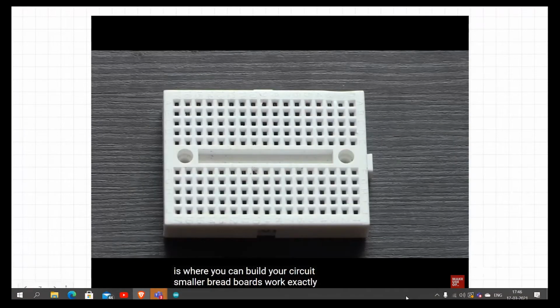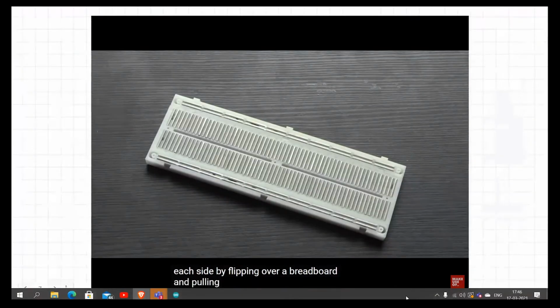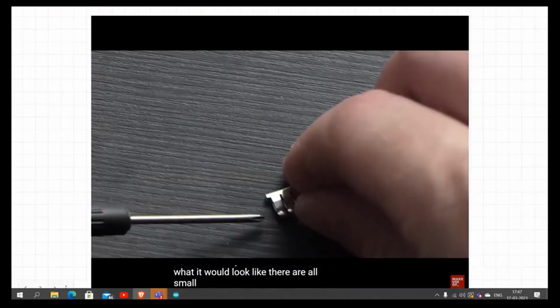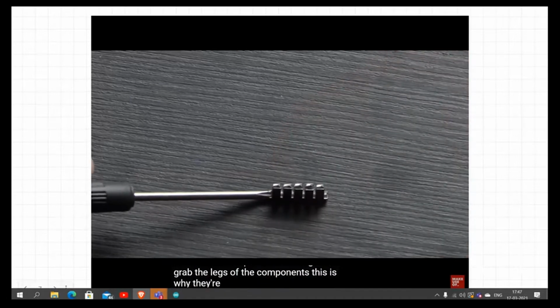Smaller breadboards work exactly the same as the larger ones, though they don't have the power rails running down each side. By flipping over a breadboard and pulling off the backing, you can see how they work. These pieces of metal run all the way along the board and connect all of the components together that you need. If you were to pull out one of the metal lines on your breadboard, this is what it would look like. They're all small metal crimps that are designed to grab the legs of the components. This is why they're so useful.